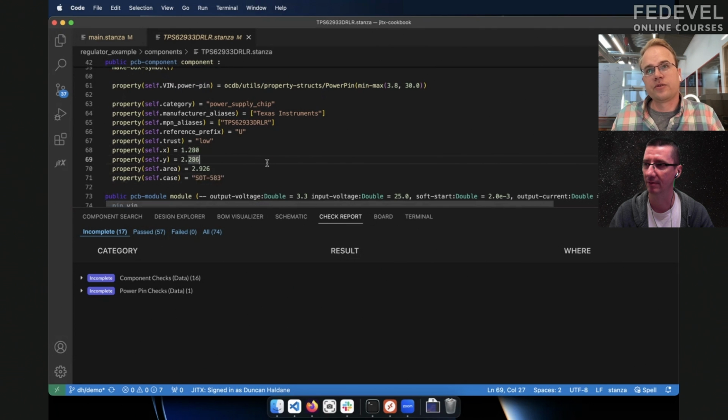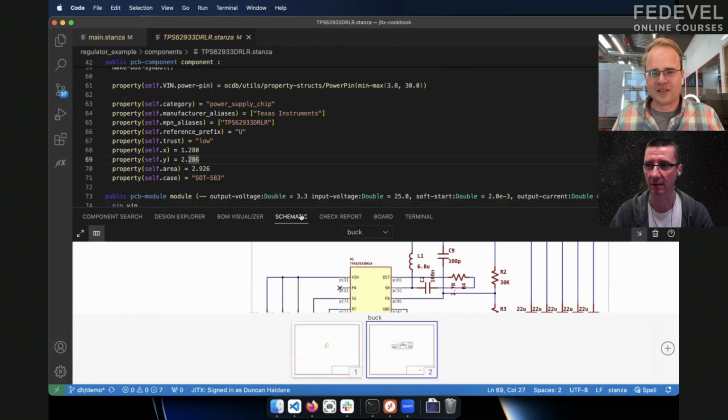And actually you can put in your operating temperatures, and it'll run a full derating analysis on all of your components. A lot of people have this checklist of, all right, here's 200 checks to run on this design. And then they try to give it to a human expert and say, okay, go check. And humans don't work very well that way. It's just not a thing that people really like. This would be very tiring, to check everything.